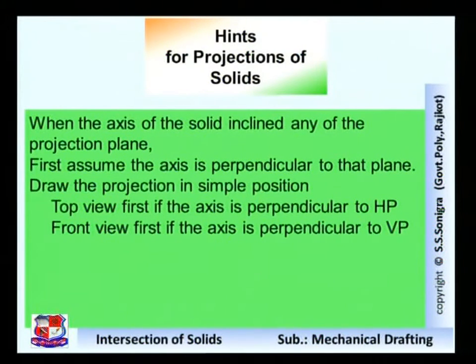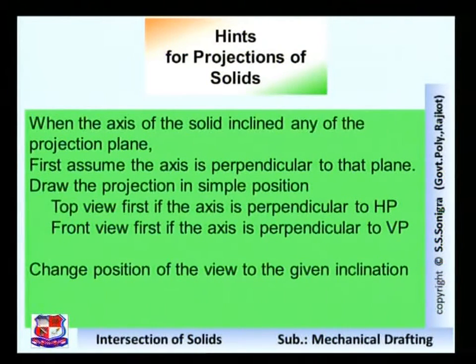And if it is given that it is parallel to HP and VP, which view should be drawn? Yes, it's a side view. The side view should be drawn first. Change the position of the view to the given inclination if needed. Whatever inclination is given, change that position.